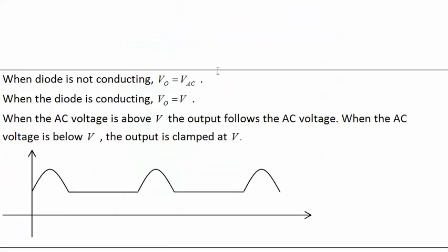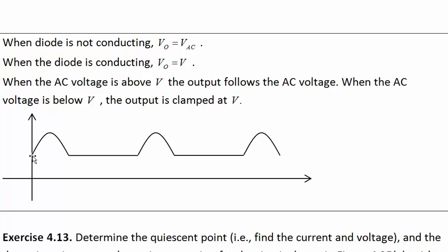Looking at the plot of this, we've got the AC voltage for a quarter of its cycle, not quite a quarter of its cycle, till it gets to half of its height, a little bit more than a quarter of its cycle, then dropping down and back up. During the parts that the AC voltage would be less than 0.5 of its max, the DC voltage clamps it from dropping any lower.